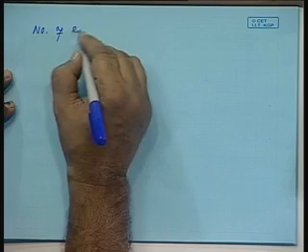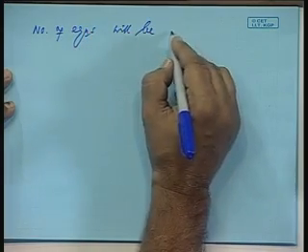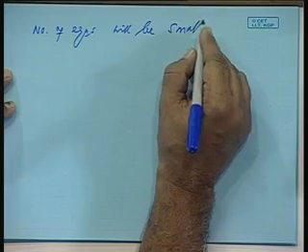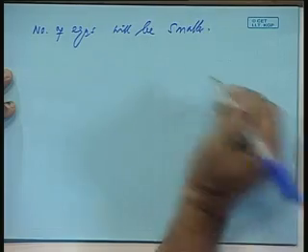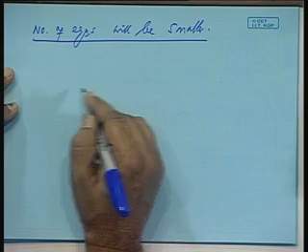So, there are m equations and m unknowns, the loop currents. So, you can write in the matrix form and then we can solve by taking the inverse of the matrix. The number of equations will be smaller. This is the most important advantage of this method.